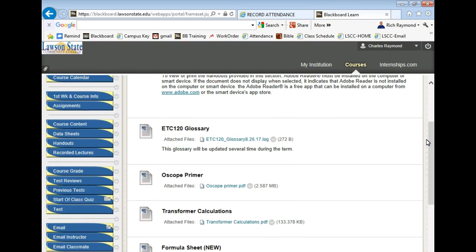And the main section of this course is learning how to read data sheets. If you know how to read data sheets, then you know how to substitute parts. So when you have a part that goes bad, you don't necessarily have to replace it with the same device, right? All you need to do is replace it with a device that's got an equal or better specification. As long as you don't go below the specifications, you're fine. A lot of people don't know that.